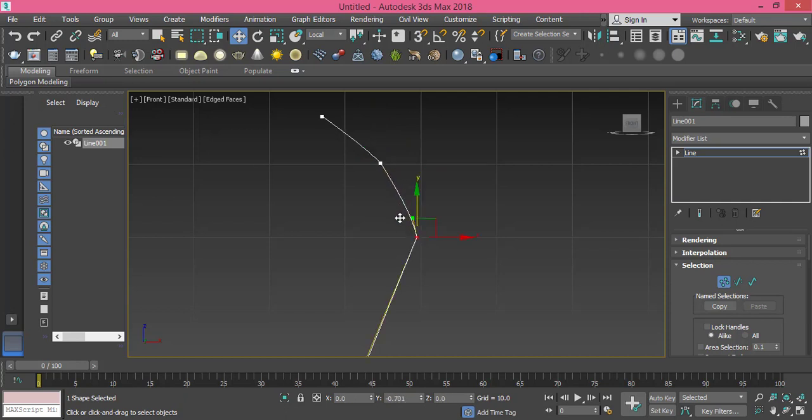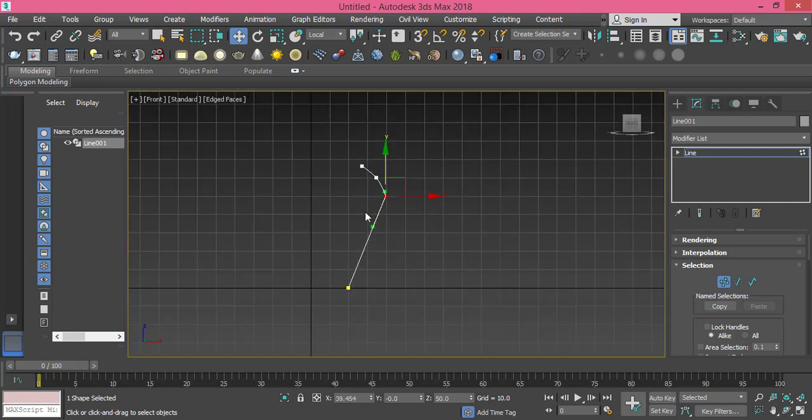Let's do slight modifications just like that. That guy needs to go up and then right. That's it. Now to create a geometry using splines, we need something called Loft, but we need 2 splines to create it. So I go to top view, or maybe I can create it here in this view.